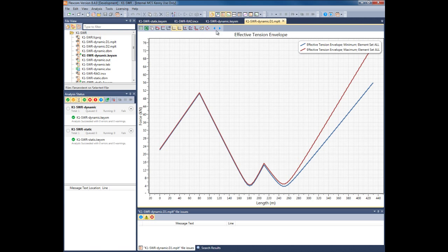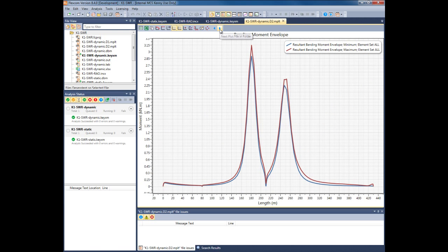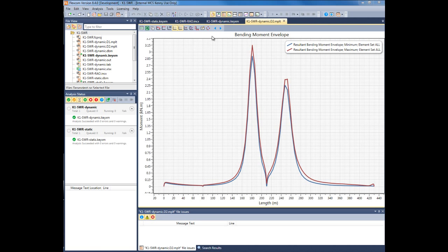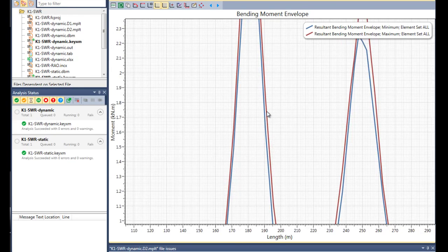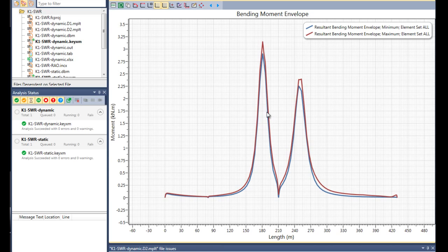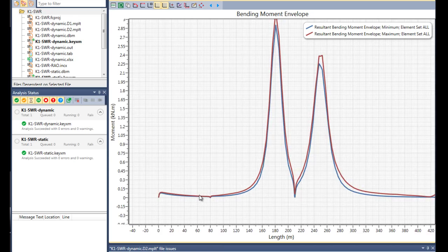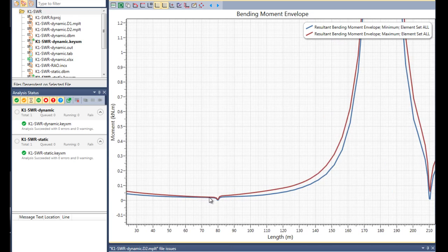The plotting tool provides several options for zooming in and out. The quickest is probably to simply use the mouse scroll wheel. Alternatively, you can hold the Control key while dragging the mouse, allowing you to select a particular zoom area. You can pan the view by holding down the left mouse button, and the grid and axis move in accordance with the mouse movements.